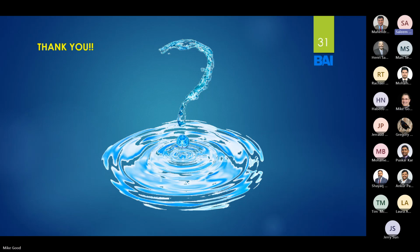So we have to use a lot of engineering judgment there. We cannot just assume one. It is really state of the art. So I have another question. Suppose we have given you some value of scour. Say Mahindra gave you a scour value of 18 feet for piers, and for the abutment he has given you 8 feet. Considering those are the critical values, the highest values you got from various formulas, how much deeper would you go compared to the scour values given by the hydraulic engineers?